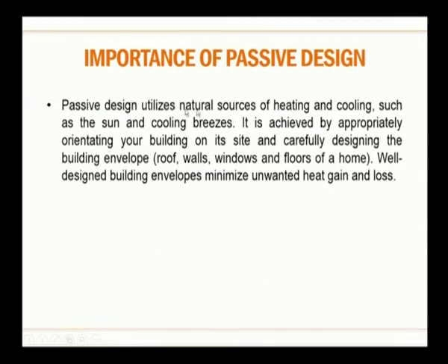Passive design utilizes natural sources of heating and cooling such as the sun and cooling breezes. It is achieved by appropriately orienting your building on its site and carefully designing the building envelope, roof, walls, windows and floor of a home. A well designed building envelope minimizes unwanted heat gain or loss.